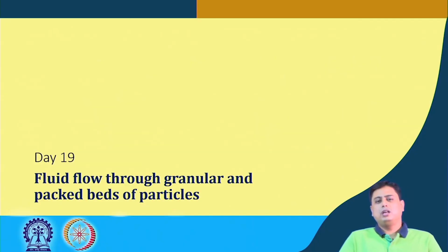But in general, if we remember the relation when the viscosity or the density changes with temperature, then we can derive a relationship for what the pressure gradient in a packed bed of granular particles would be, and how del P varies with temperature, because temperature essentially changes the density or the viscosity, that is, the physical properties of the fluid phase.